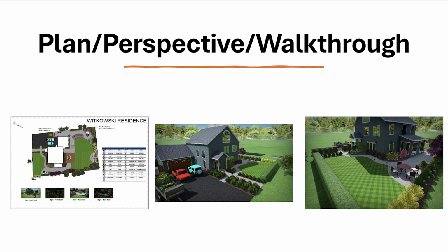Similar to Dynascape, this takes place before the drawing is started by drawing a square to determine the printed area. This view is what is printed out after the drawing is completed. Our print scale was 1/8 of an inch equals 1 foot, which means that 1/8 of an inch on the paper represents 1 foot in real life.